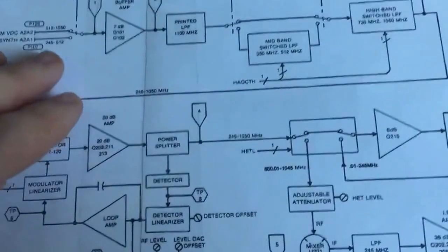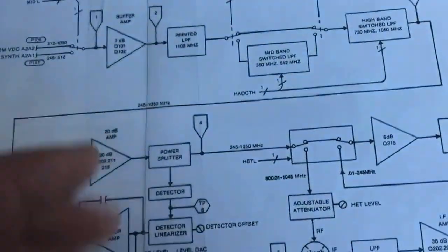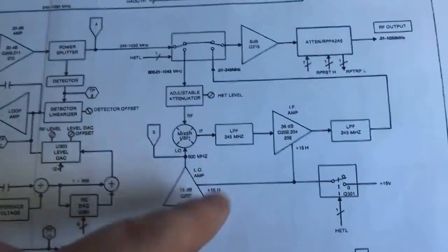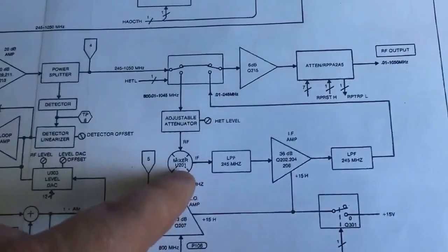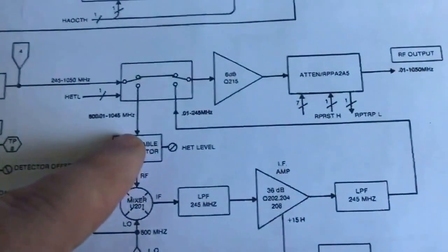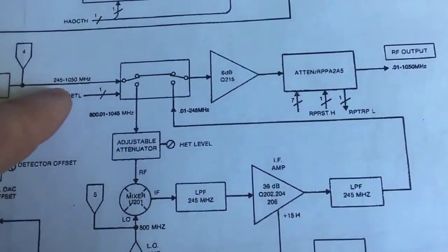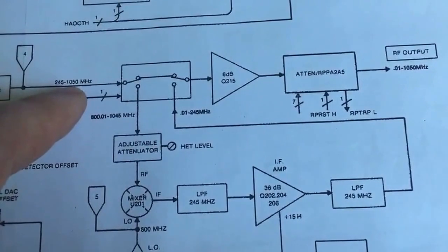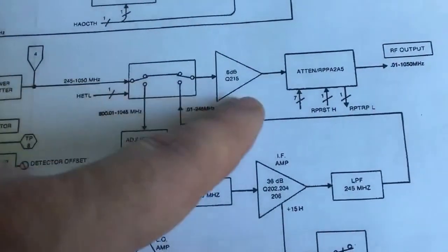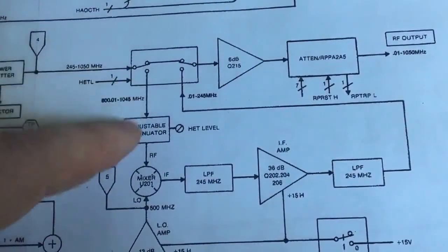So I was trying to find out where the 10 megahertz error was coming from. So I was going through the bands and I thought, right, well, the 800 megahertz VCO here, that's just for a mixing signal. That's all it does, right? It's a fixed 800 megahertz. It turns off when it's not needed. So if I come in here a bit more, when you're on between 245 and 1 gig, well, 1.05 gig, it goes straight through, right? If you're on anything other than that, it comes through this mixer,